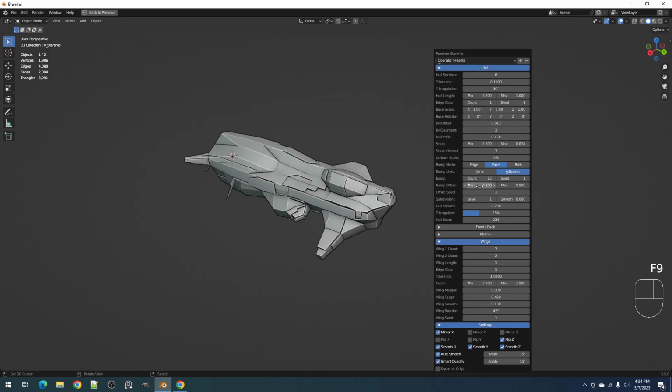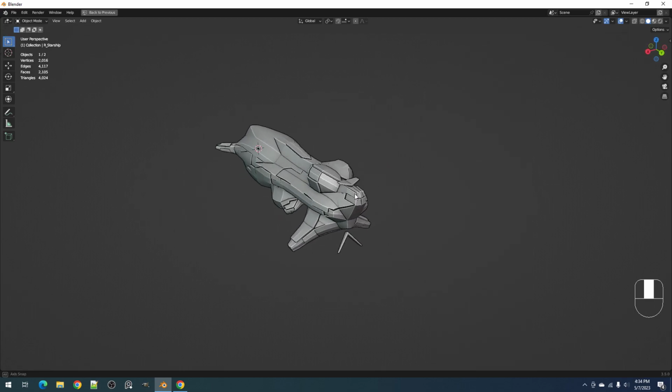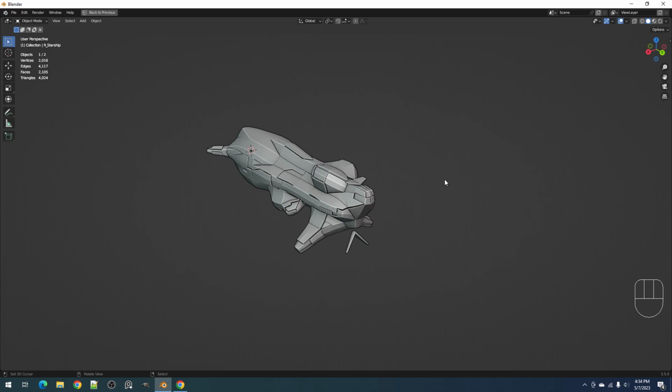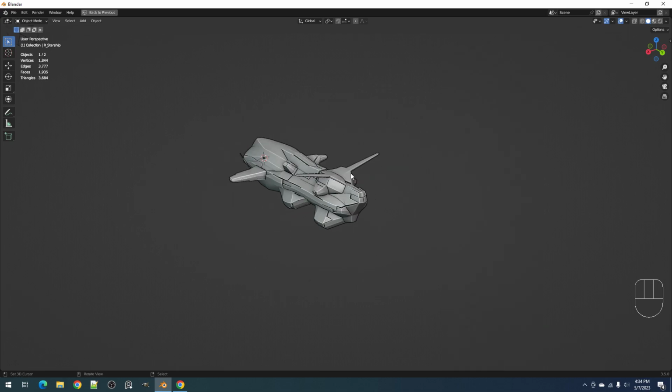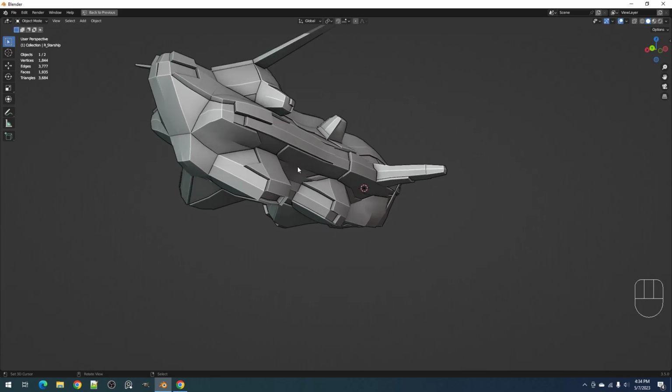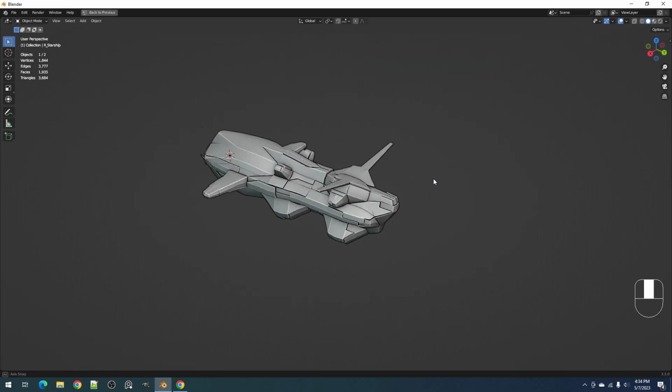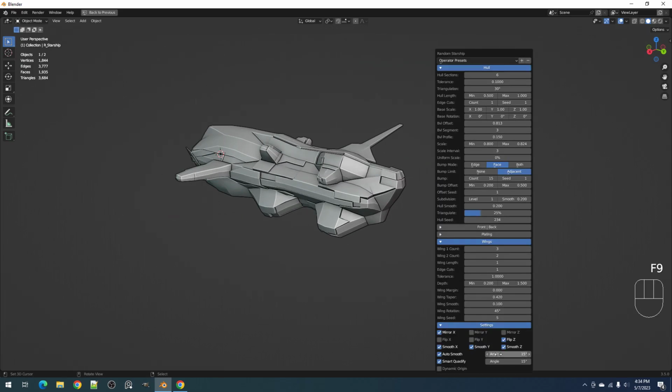Okay, let's soften it up using geometry smoothing, or subdivision smoothing, 0.2, and 0.2 in the hull smooth as well. We got disconnected geometry there. Those are the wings, so we can randomize them out. There we go. And for these hard faces here, we can play around with the auto smooth value.